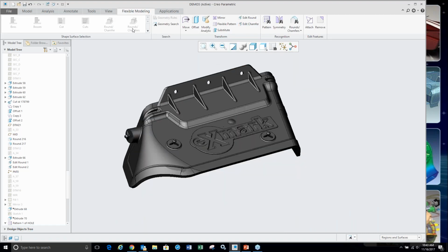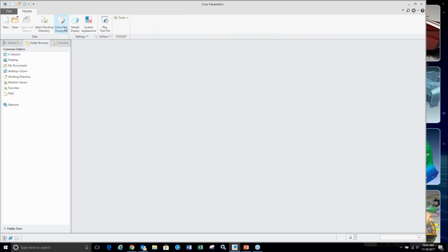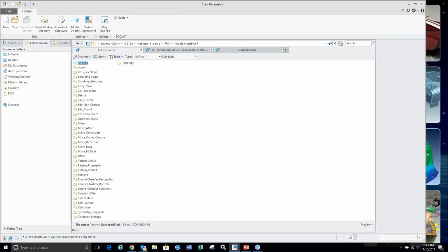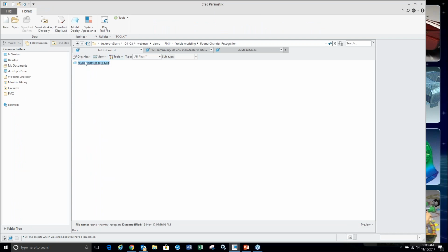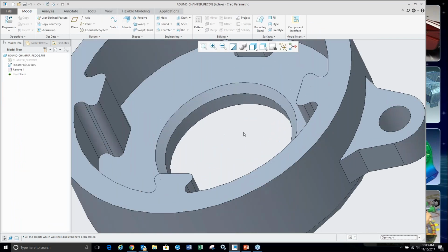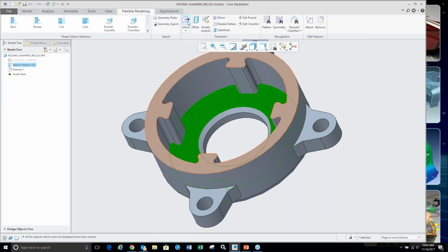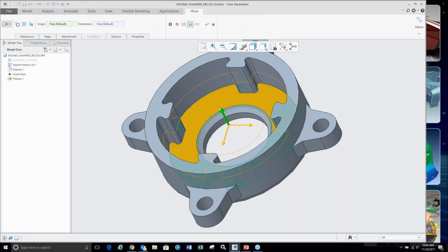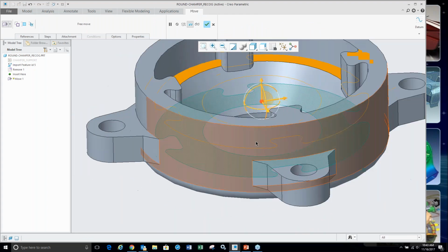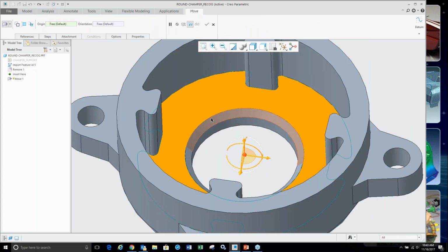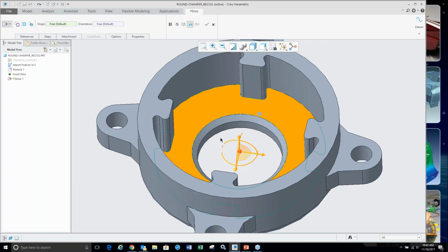So you have editing tools. You can even recognize them if it didn't recognize. For example, if I could go to a design like this, I'm trying to do an offset on this. Let's say I want to move this. I move this. When I move this, something that shouldn't happen is happening. You see the chamfer. There is a very small value that's getting extended. The reason is it's not identifying that bevel surface as a chamfer.